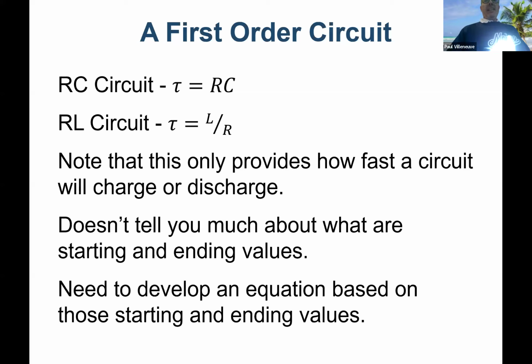Yeah, seconds, because it's a time constant, right? So the units have to be seconds. And the nice thing that a time constant does, because when you actually come up with a solution, it's not written as a time constant. When you solve for it using differential equations or Laplace, you end up with the inverse of that. But using the time constant gives you an indication of how long something takes to reach steady state. So the bigger the time constant, the longer it takes for that system to reach steady state. And what I mean by system reaching steady state is that the system is fully charged or perhaps even discharged. Okay, that's the concept of a time constant.